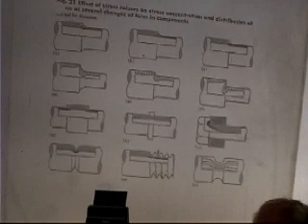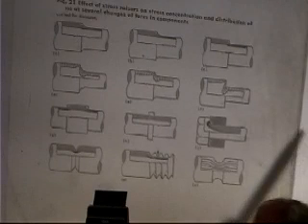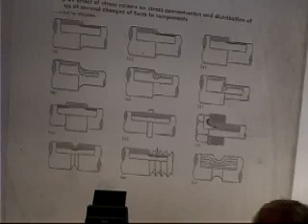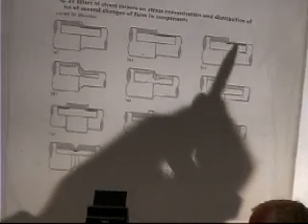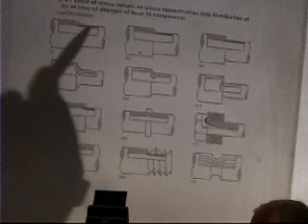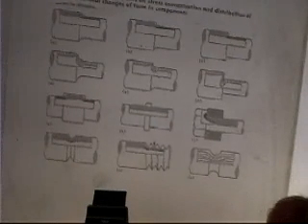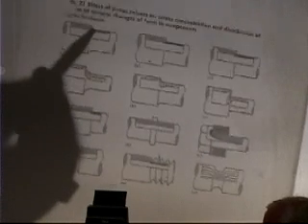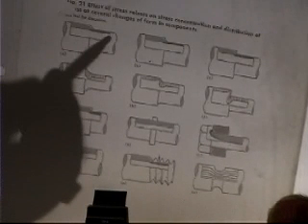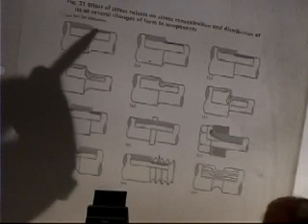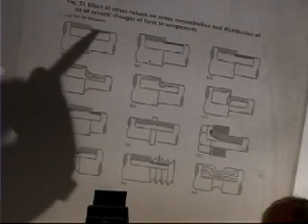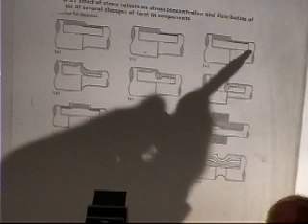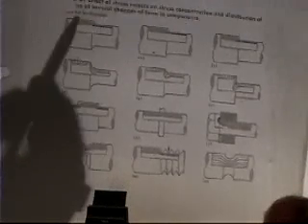If you really want to know, since we're sitting in a math classroom, if you solve Laplace's equation, if you have a good feel for Laplace's equation, you will find that things bunch up around corners. Whereas if you solve Laplace's equation in something that's gentle, you'll find that they don't bunch up in the corner. You can have a nice continuous change from high stress to intermediate stress without everything trying to turn around the corner and get bunched up. You can see how things get bunched up even tighter around the corner than they would be here in the higher stress region. Whereas here, they're not bunched up as much.